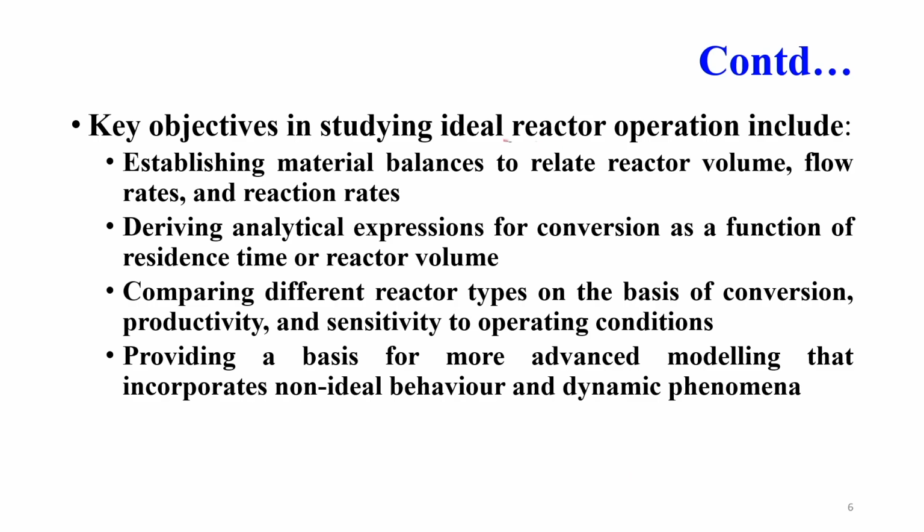Now, what is the objective to study this ideal reactor operation? First, we can establish material balance to relate reactor volume, flow rate and reaction rates. So, material balance: inlet, outlet, generation and utilization should equal the rate of accumulation. It helps us to derive analytical expressions for the conversion as a function of time or reactor volume.